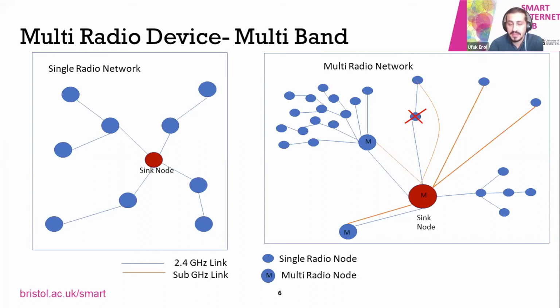Another advantage of using that is the radios can work simultaneously to process the data. So each node doesn't have to wait for the next slot frame to process the data. They can use both radios to process the data at the backhaul. So it gives extra bandwidth, and extra capability to the network. We can lead to mobility as well.